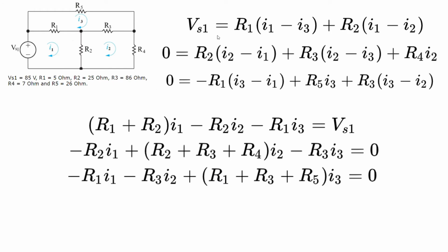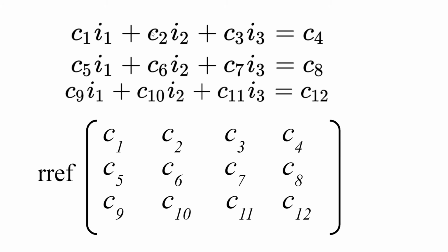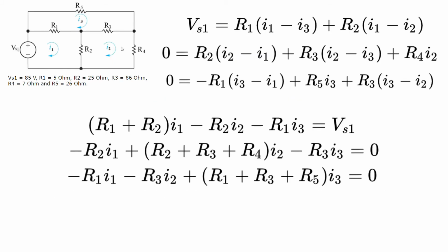So this is how we generate the three equations, right? You should all be comfortable with this. This isn't MATLAB stuff. This comes from the circuit around I1, VS1. It's just how the mesh analysis works. But this isn't actually what we're putting into MATLAB. We need to put it in the form that we saw earlier, where our I1s are all separate, and they're all being multiplied by a single number. So that's exactly what this is. Just very, very simple algebra to get from this step to this step.